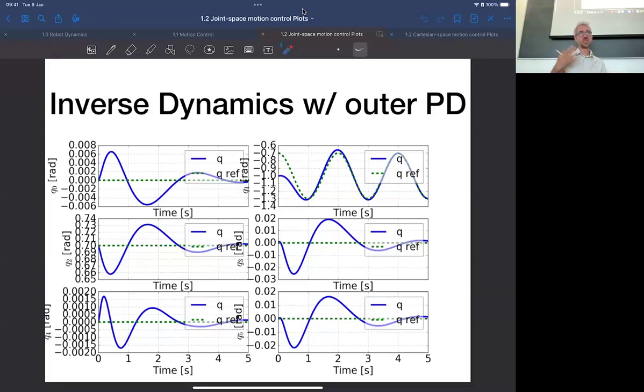So you have a loop because you're working on a computer, so time is discrete and computation takes time. So you cannot update your controller every nanosecond. You typically operate at frequencies that range between 100 and 1000 hertz. So even if the control frequency is very high, it's not infinitely high. And so there is already a source of, let's say, uncertainty, or an unmodeled effect.